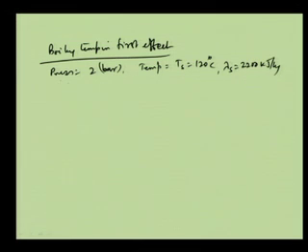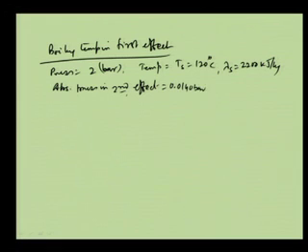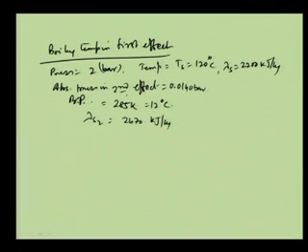And then the absolute pressure in the second effect is equal to 0.0140 bar. So, the boiling point of water will be 285 Kelvin, that is 12 degree centigrade, and then lambda S2 will be equal to 2470 kilojoule per kg.